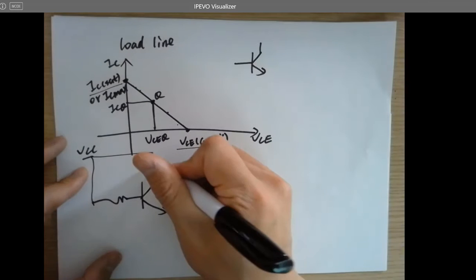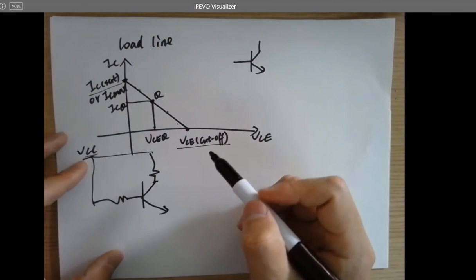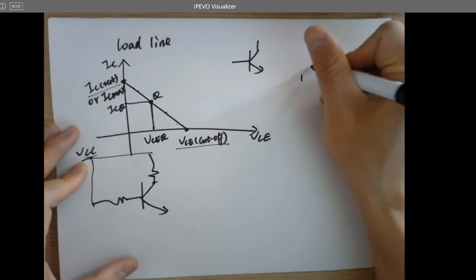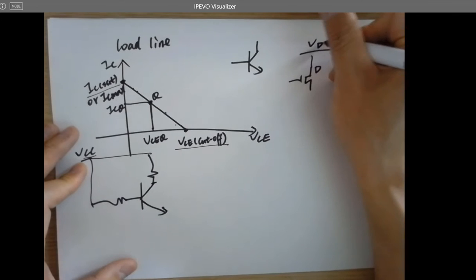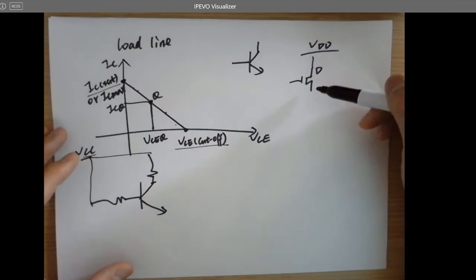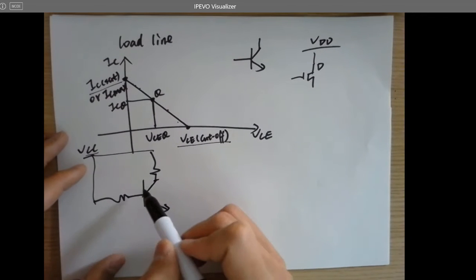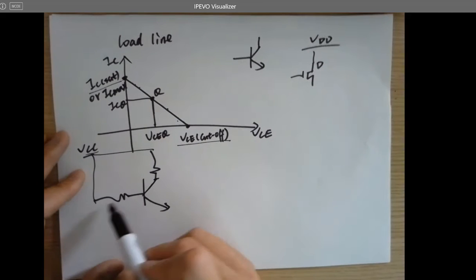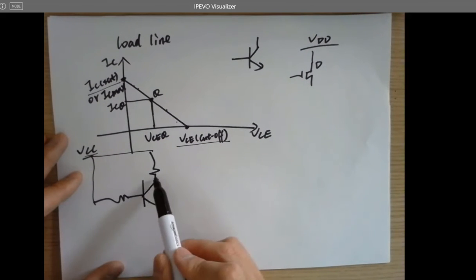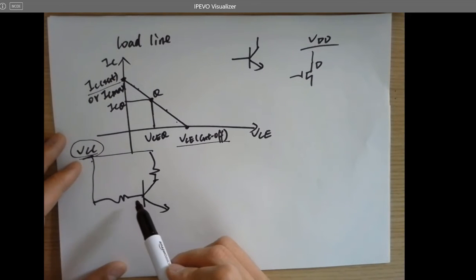This is a collector, right? It says collector voltage. That's why it's called VCC. And for NMOS, that's the drain. So all these top rails are called VDD because it's a CMOS logic. Here's a collector logic. It's a BJT logic. So it's called VCC. If I bias the base and also the collector at VCC, just using the same voltage source to bias it,